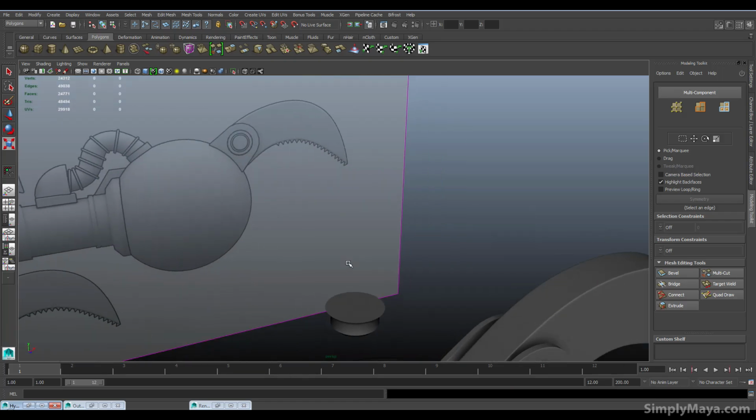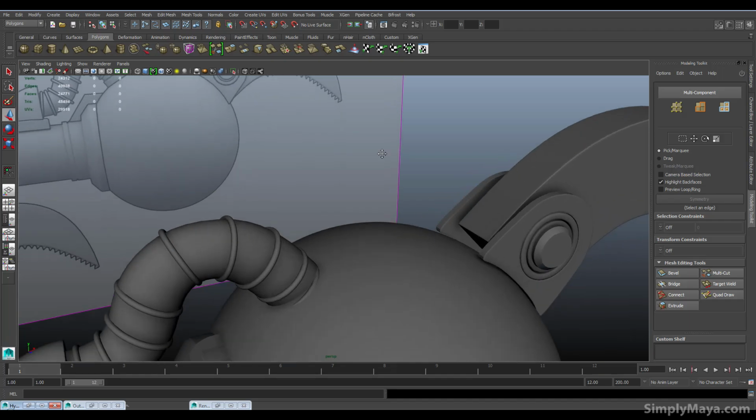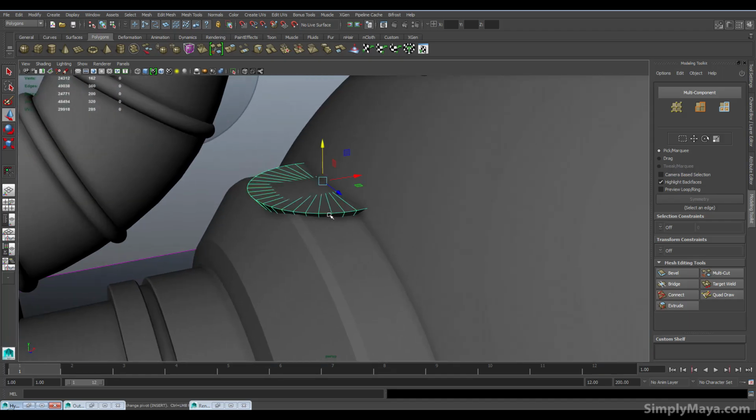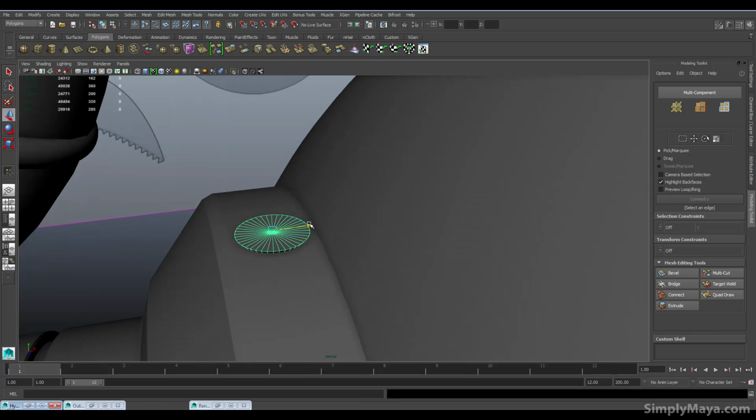Okay, now I'm going to take this and I'm going to use it as a drill bit, and that will make perfect sense in a moment. So let's pull this back to here, and for now I'm going to hide this piece, and I'm going to scale this to the right size. So let's scale this in and get it into position, and this will be the position of where I want my hole drilled, and soon this reverse boolean will make sense, I hope.